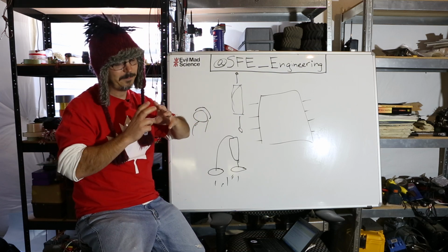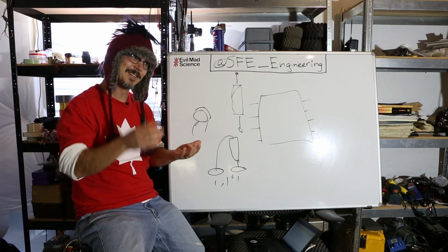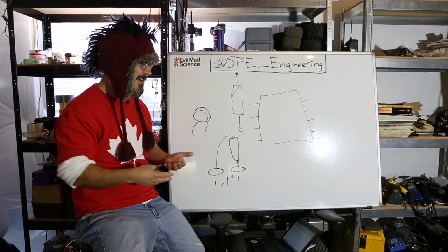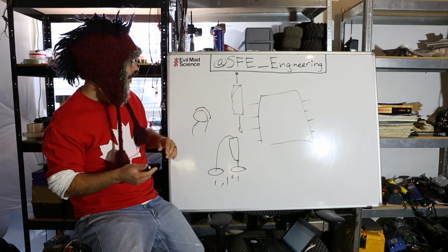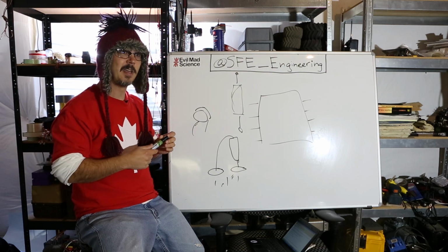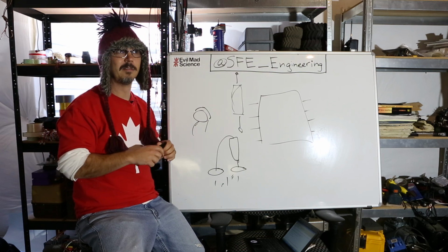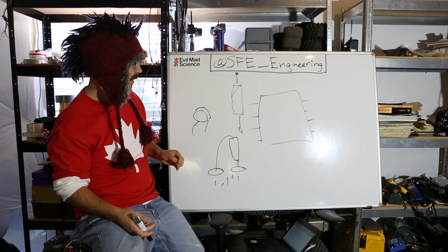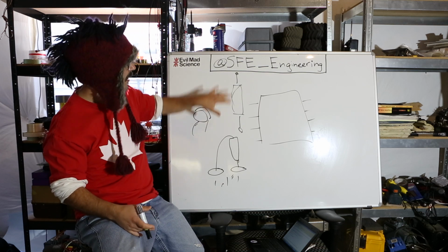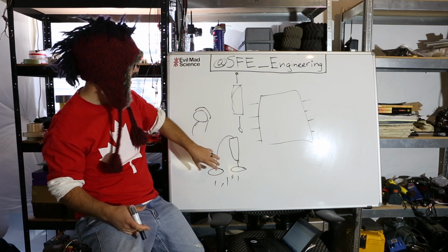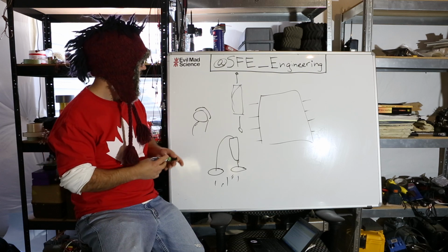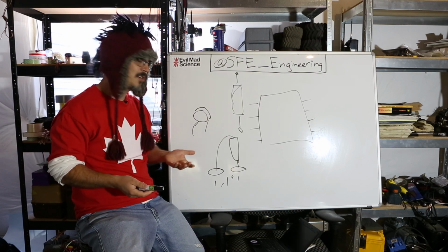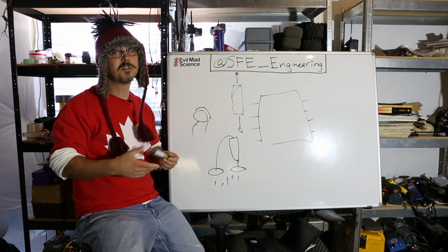Although you can get big sizes that will also be surface mount and take up not very much space. But there's still a lot of pieces that are only made in through-hole design, so you can get a good heat sink on them. So you may still be constrained to use some through-hole stuff. In terms of resistors, again, if it's not a power consideration, you can go to a surface mount part.